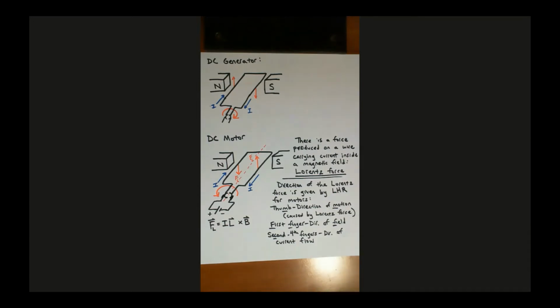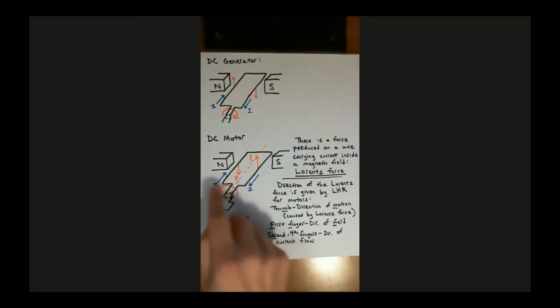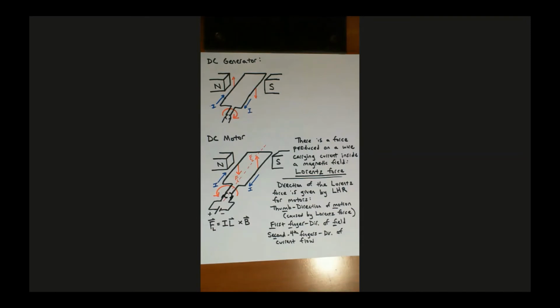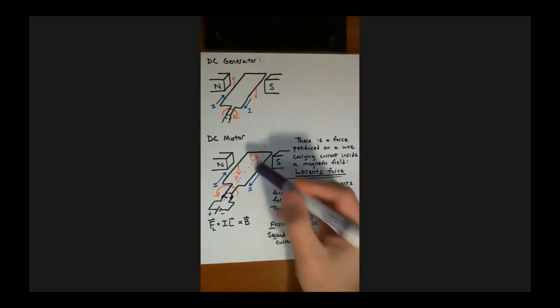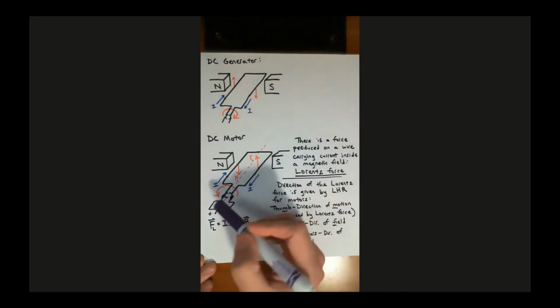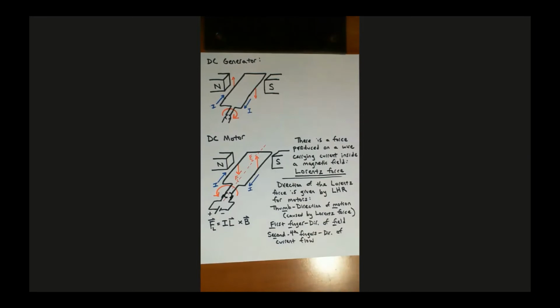All right. So now the question is, what's limiting that acceleration? Is this going to continue forever? Is it going to accelerate in the counterclockwise direction forever, indefinitely? And usually the answer that I get for that is no, because there's air drag, there's resistance as this armature is rotating around, there's drag from the air. There's also some resistance in the bearings. There might be a bearing over on this side and probably a bearing on this side too, or a bushing or something. And there's drag and resistance there too, so that's going to limit the RPM.